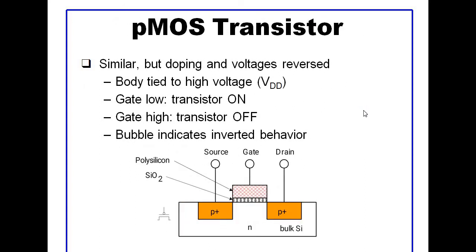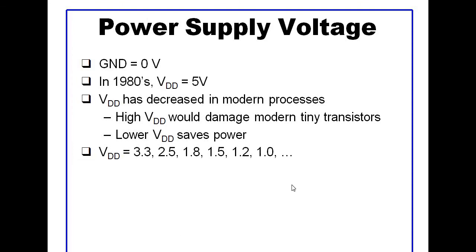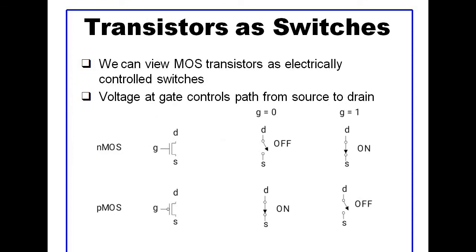In the case of a PMOS transistor, when the gate is at high potential, the source and drain regions are reverse biased, so no current flows and the transistor is off. Also in a PMOS transistor, a low gate voltage inverts the channel and a conducting path of positive carriers is formed from source to drain. So the transistor is on.